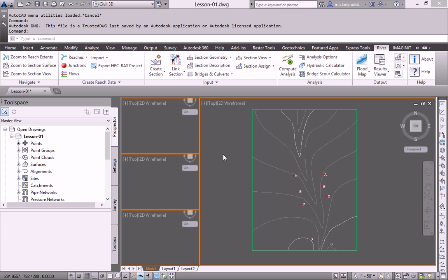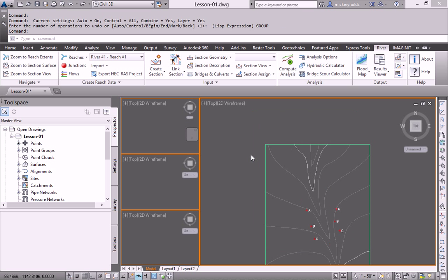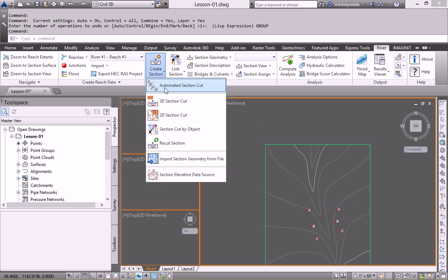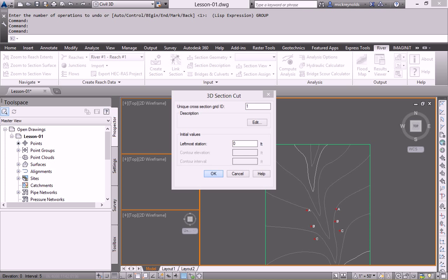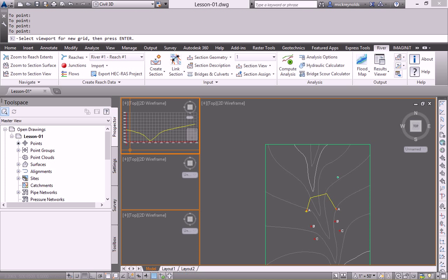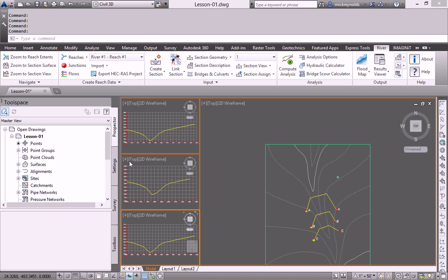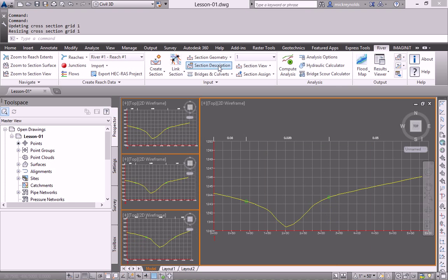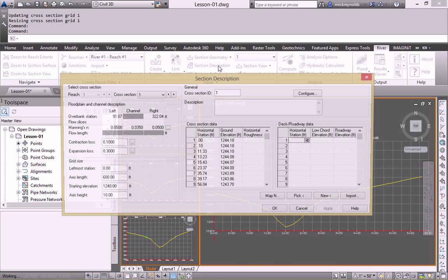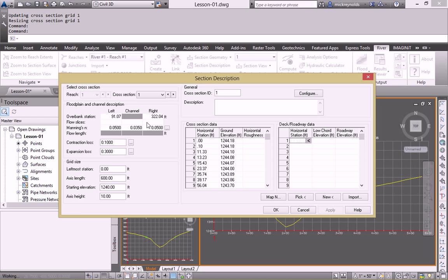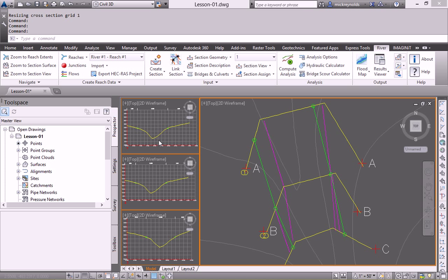The last hydrology tool we'll look at is the River and Flood Analysis. This module allows you to evaluate reaches in streams and rivers using HEC-RAS. The user can start by creating cross-sections and profiles of those cross-sections. We can define the overbank characteristics for each one of our cross-sections and also digitize the overbank locations in the